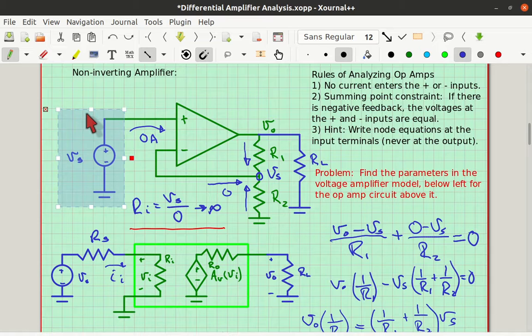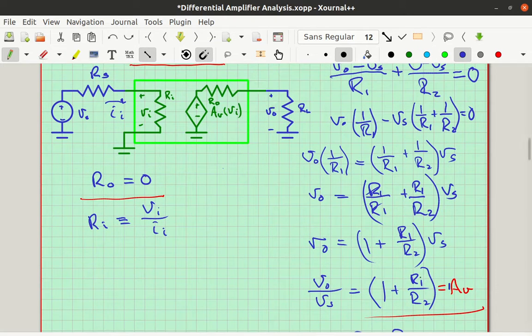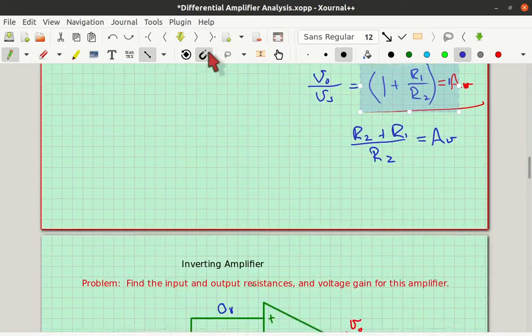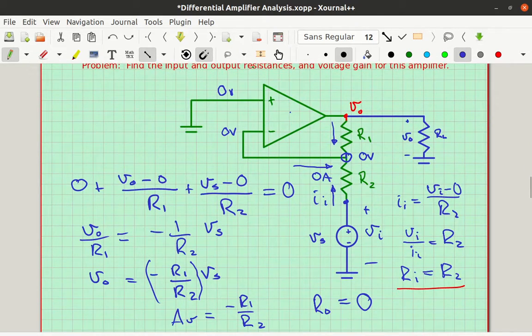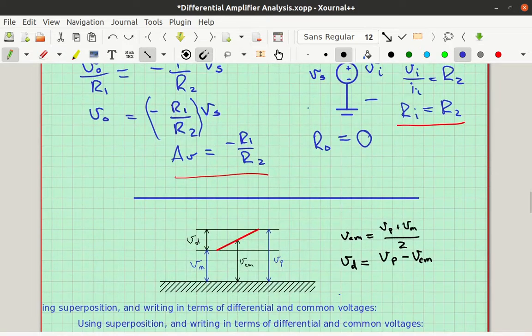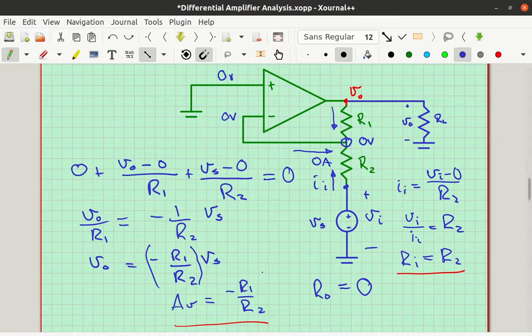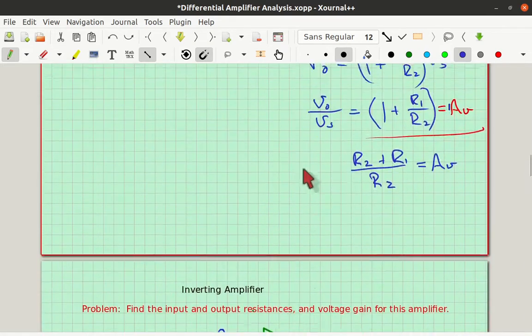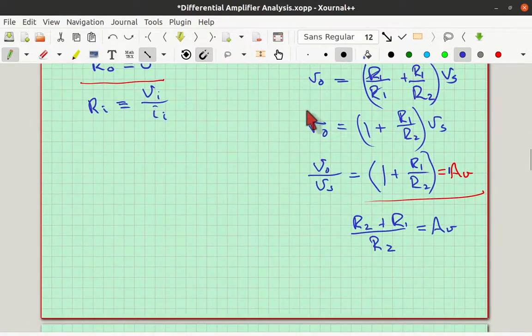Now the idea that this sparks is that perhaps you could hook up both input voltages, and one of them has a positive gain. That's the non-inverting amplifier. That's this guy right here. This number is always positive. And the other one has a negative gain, which would be the gain for the inverting amplifier, which is right here. And you will also notice that the inverting amplifier has its gain in magnitude as R1 over R2, while the non-inverting amplifier's gain is actually 1 plus that right here.